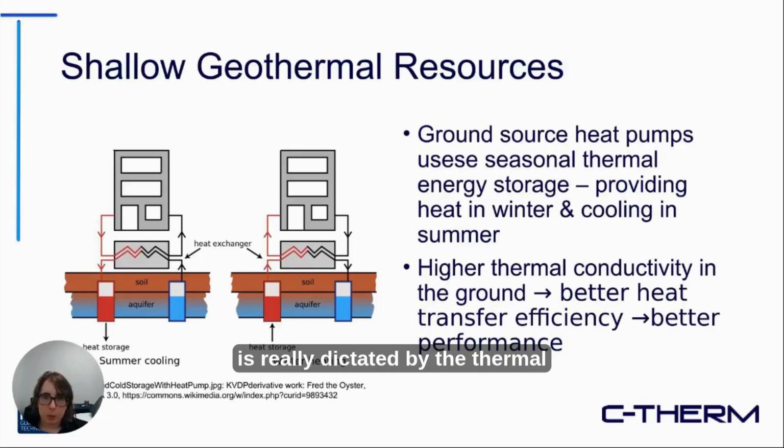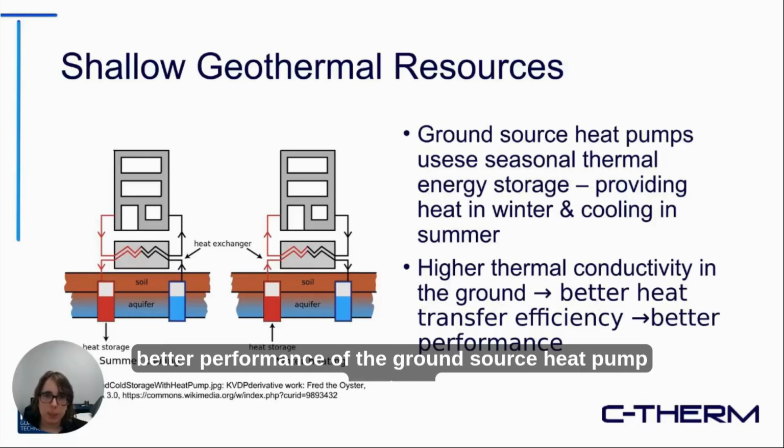In this case, the suitability of a basin for this type of application is really dictated by the thermal properties of the basin. If you have a higher thermal conductivity of the reservoir in the ground, you'll have a better efficiency of your heat transfer, and therefore better performance of the ground source heat pump system.